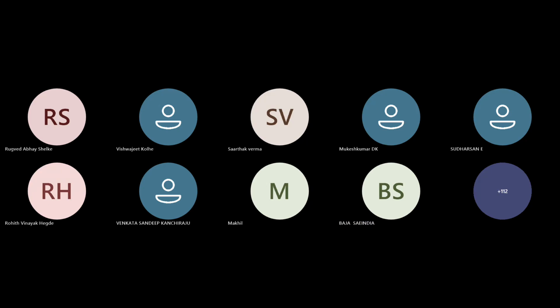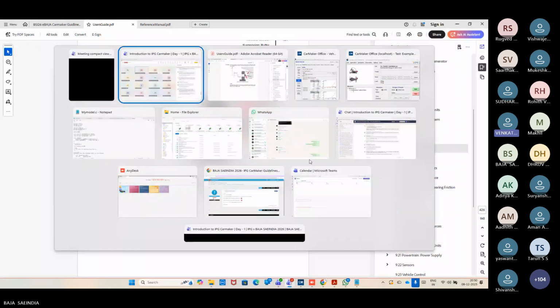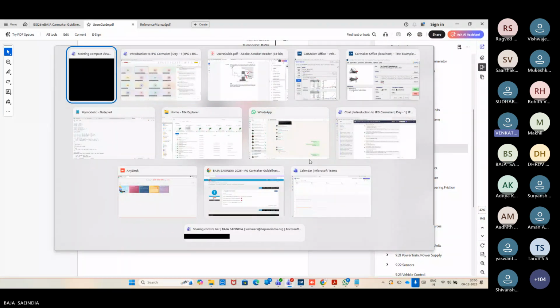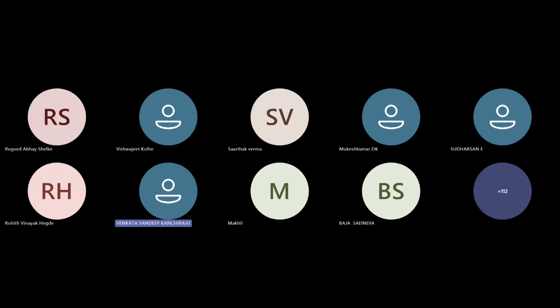While entering the mass of the vehicle in the vehicle data generator, we enter the total mass initially, but after separately adding all the other masses, we ended up with an overall mass of 500 kgs in the info. Should we also add roll cage mass in the vehicle data generator, or have I made some mistake? Basically, first you measure your vehicle's individual component weights.